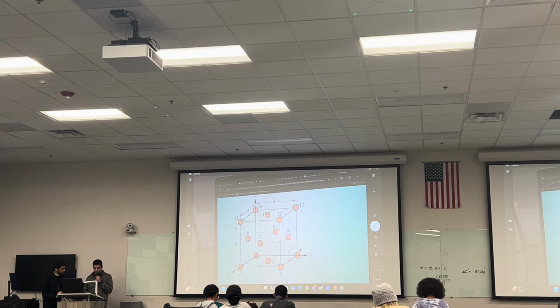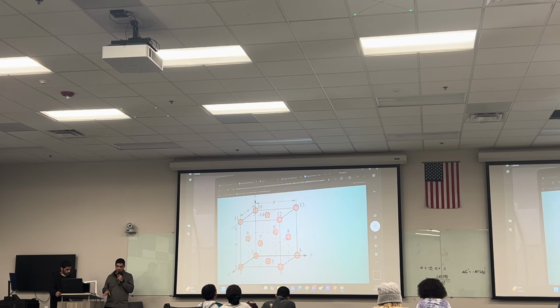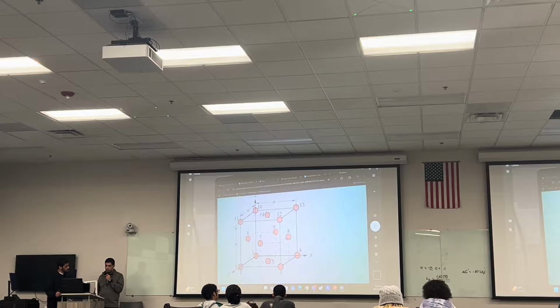So if number 1 is the origin, 0, 0, 0, what would be the coordinates of number 4? Exactly, 0, 1, 0. It's the same thing. If it's asked for number 5, you have 0 for the z-axis, because it's in the xy plane, and since it is centered, we have an FCC structure. The center, so you would have, again, half for each x and y coordinate.